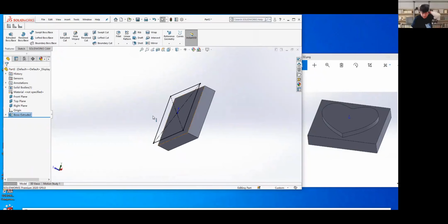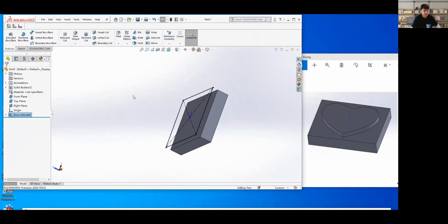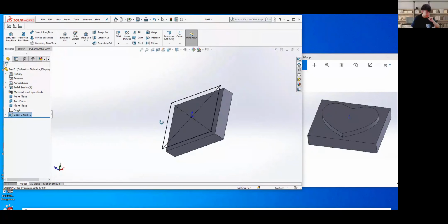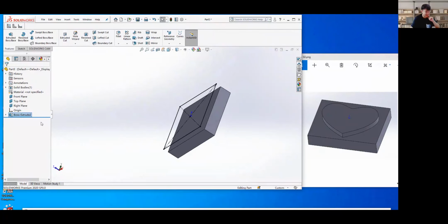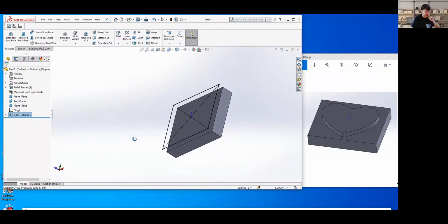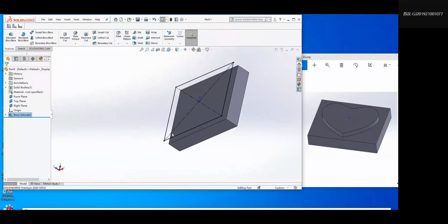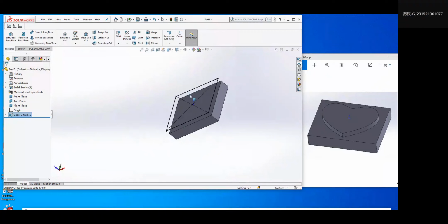So it's okay for you guys to not select the sketch first and just do the extrude, but it's convenient to select it first. But I saw sometimes, if I don't follow the rules correctly, I get some error, like it's not working. Yeah, sometimes there will be an error because you didn't select the sketch. So it's better to go back, select the sketch, then extrude, to make sure, okay.